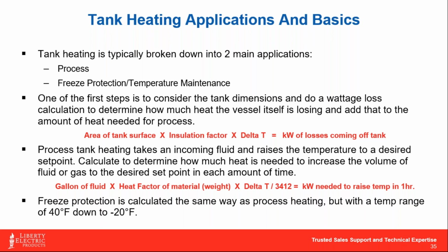There's either, I need that fluid to come up to temperature at a very fast rate. If I need 5,000 gallons heated up in 1 hour's time, it's going to be a much larger heater involved for that type of challenge versus, once I've got the tank up to 100 degrees, I just need to maintain it at 100 degrees, where we can get away with using a much smaller heater that, hey, it may take 2 or 3 days to heat that load up entirely. But once you've achieved it, based on your flow rate coming out of the tank, a smaller heater can often keep up with that process application.